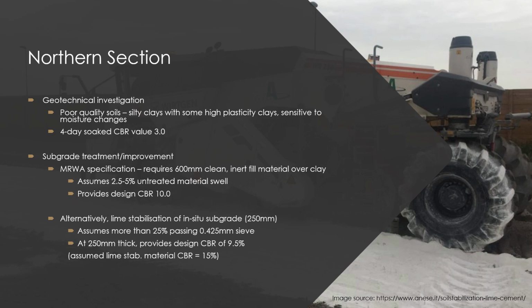Now, as per Main Roads specification or Engineering Road Note 9, clays of this nature are assumed to have 2.5 to 5% untreated material swell. It does require 600 millimetres of clean inert fill over the clay.